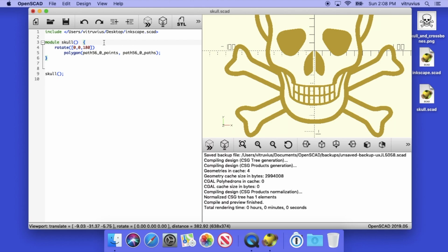Now, this is a neat little function of OpenSCAD. We type resize, and then a left paren and then a left bracket because we're going to type some X, Y, Z dimensions again. And so we type 0 and then 50 for the Y dimension and then 0 for the Z dimension. A right paren, and then we type auto equals true, followed by another right paren. What that auto equals true does for us is, any axis for which we specified a 0 dimension, we're asking OpenSCAD to figure out what it would be if the resizing is done proportionally. The only axis we specified was the Y-axis. So we're telling OpenSCAD to resize the Y-axis to 50 and then calculate what the X and the Z dimension should be with a proportional scaling.